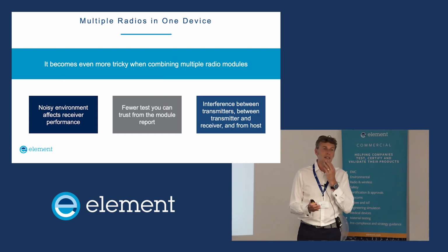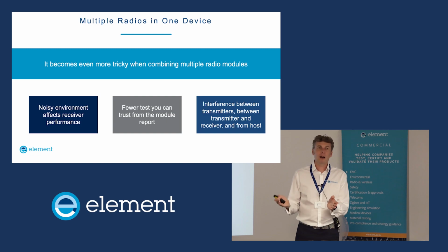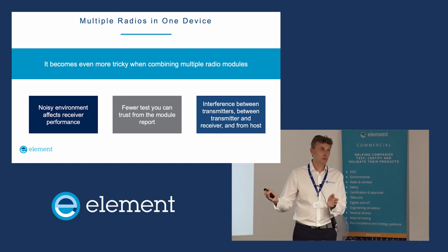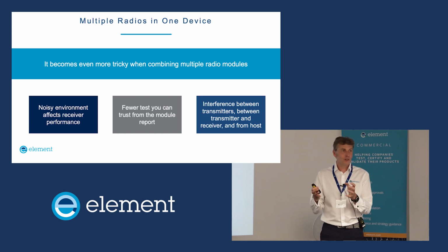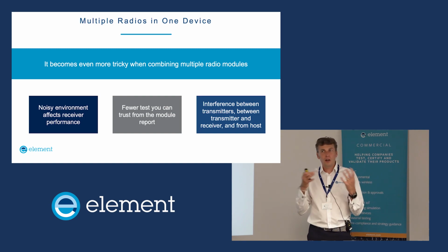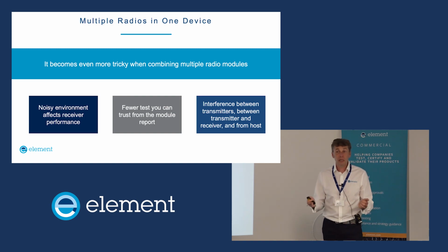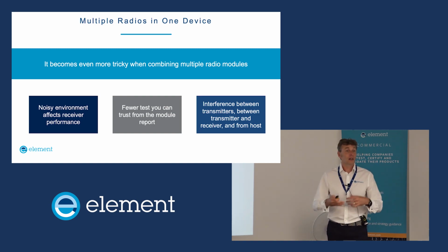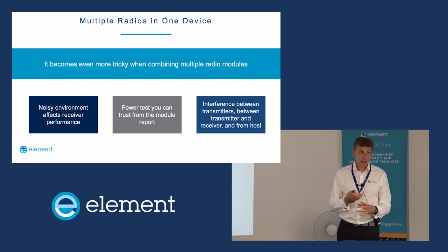Well, okay, so let's say it's an 800 megahertz LTE module. The second harmonic is at about 1.6 gigahertz, which is where your GPS is, and the third harmonic is about 2.4 gigahertz, which is where your Wi-Fi is. So suddenly, those receivers might be really compromised, and all the electronics in it. So at what point do you say, do you know what, let's go and repeat the receiver testing on the end product? And again, for Europe, that's completely your decision.